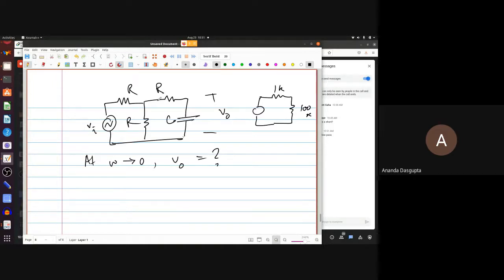Okay, there are two different options that I've got. One person has said low pass, the other said high pass. And the high pass argument is actually wrong. That's where you're confused yourself. You're saying this impedance is so high that most of the current flows through this. I would agree. But remember, once an impedance is high, it doesn't really, because remember, this one and this one